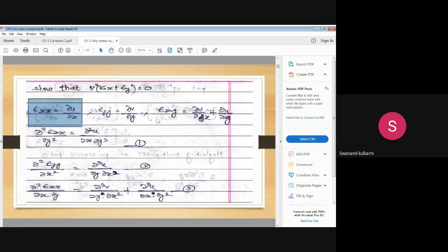So from previous concepts, now we know the strain along x-axis. During last lecture, we identified the value of stresses, the value of strains, the equilibrium equation, and the compatibility equation of the strain. While forming the compatibility equation of the strain, we went ahead with the assumption that epsilon xx, that is the strain along x-axis, is nothing but dou u by dou x. That particular concept we have proved.